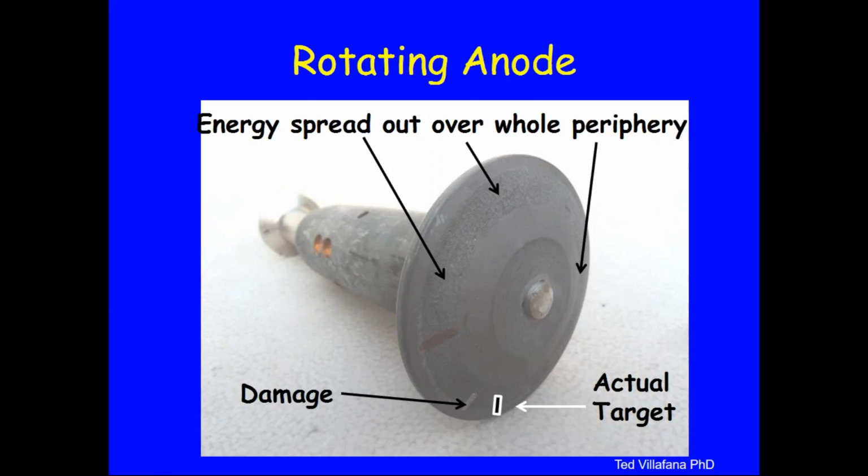wear and tear on targets is that you have a progressive pitting of the anode. That's perfectly normal, and as time goes on, you produce more and more pits. As you produce more and more pits, which are really point vaporizations of the tungsten, you do have a gradual release of oxygen, and remember, when you release oxygen, eventually pop goes the filament from oxidation damage. Talking about damage, look at the bottom of this. See this whitish area?